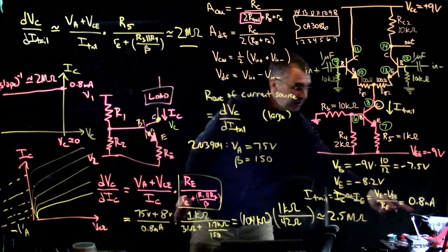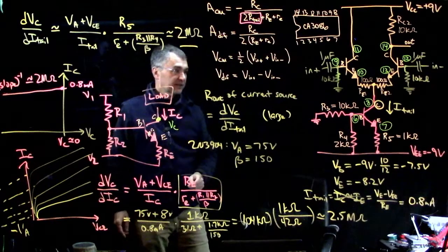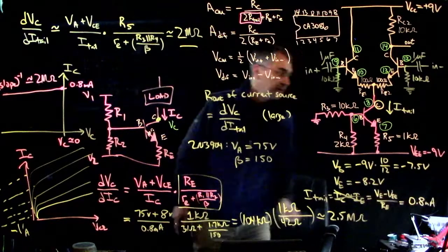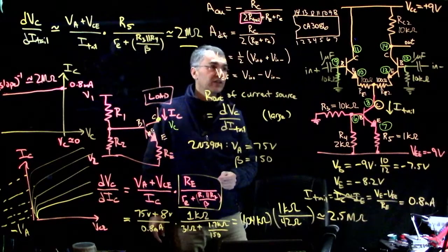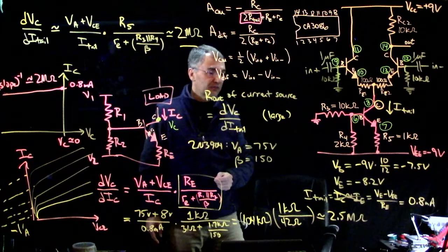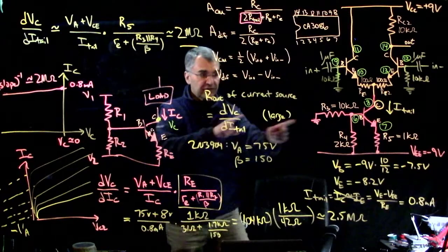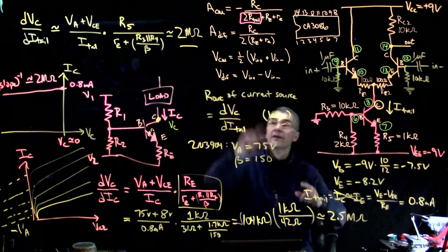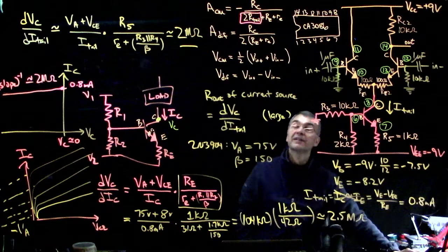But actually, we picked values that gave us a current source current which is very close to the current we had before with the tail resistor. So it basically didn't change anything for the differential gain. It basically didn't change little re. Let me go back and just remind you how we set the current in this current source, and then we'll calculate the change in the common mode gain.